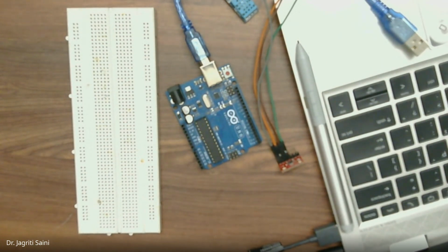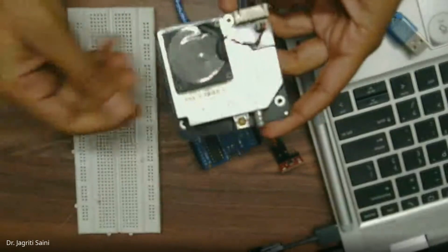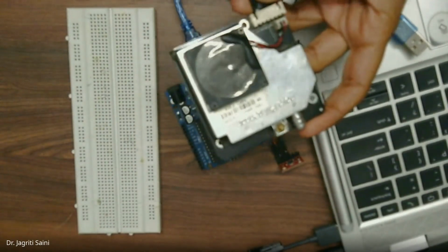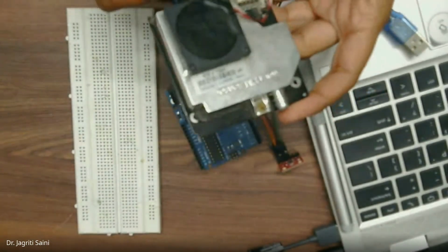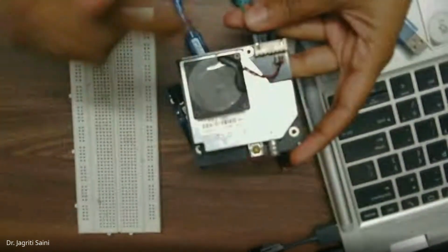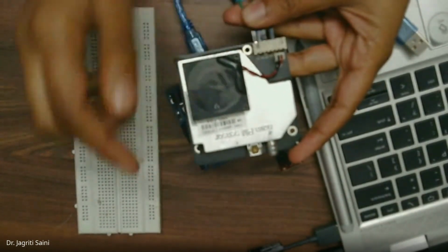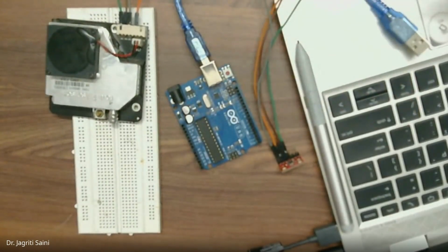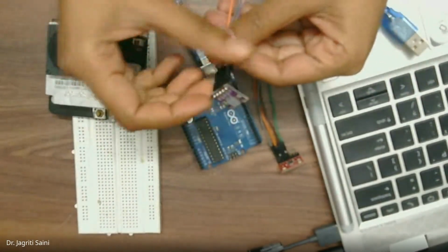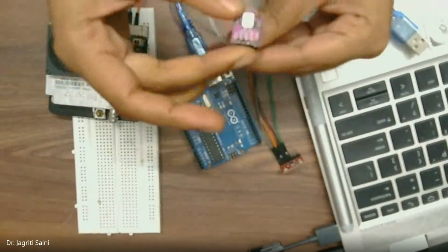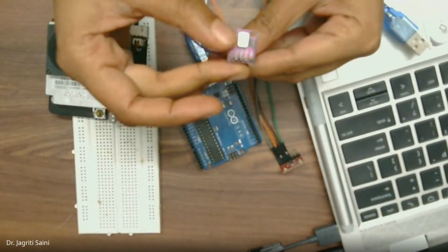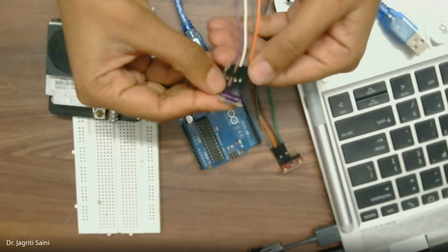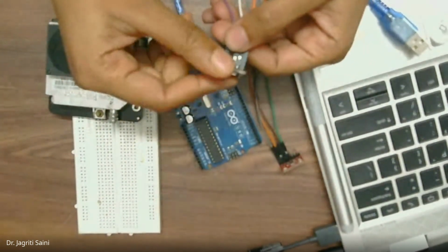Similarly, I have this sensor as my dust sensor that we have seen already. We need one more wire to be connected here for the transmitter. So we have transmitter, receiver, ground, and then VCC, and accordingly I have connected wires on this sensor as well. And then one more thing we have is the multi-gas sensor. For this one, again, 4 wires I have connected, and depending upon what measurements we want to do, I have used the pin sequences for CO and NO2, and the middle one I have kept free for NH3, since I'm not measuring that right now.